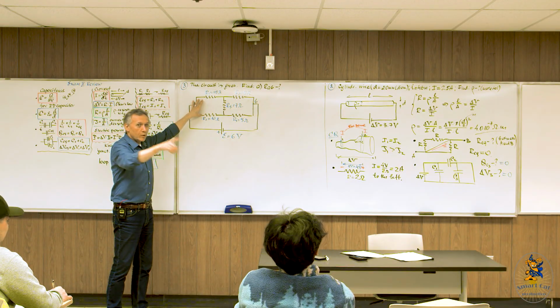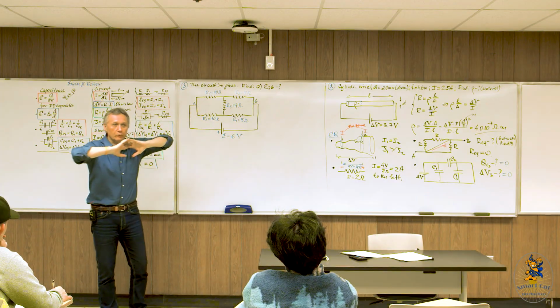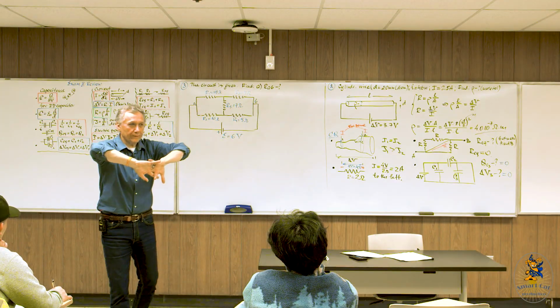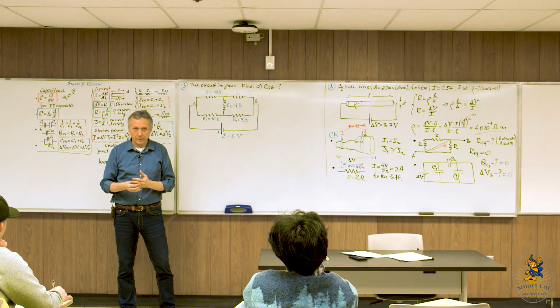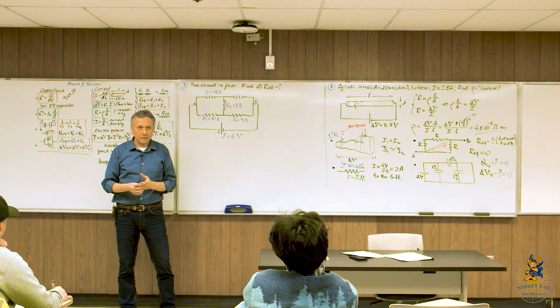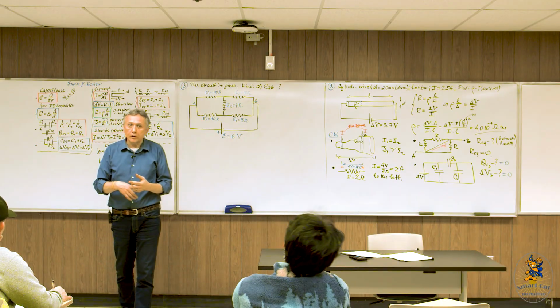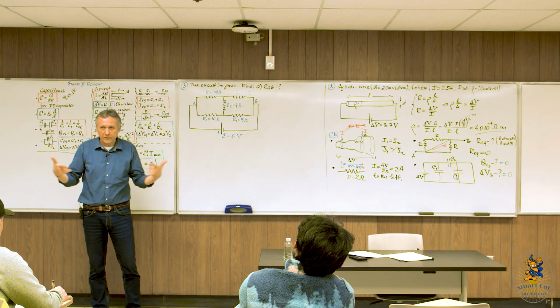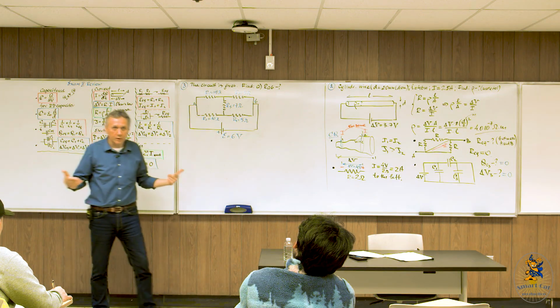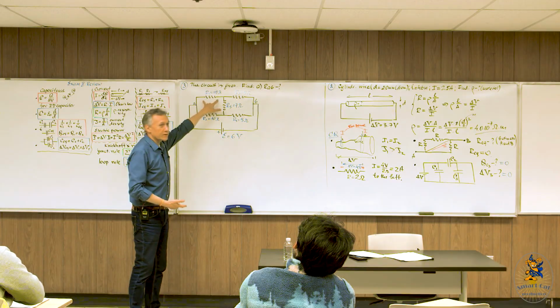Okay, guys, do you remember what we have to check in order to convince ourselves that resistors, or whatever elements you have, are connected in parallel? What's the test? Potential difference. You need to look at the potential differences because sometimes elements can look parallel to each other graphically, but from the point of view of physics, we don't care about graphical, right? We just need to check whether the potential differences are the same or not.